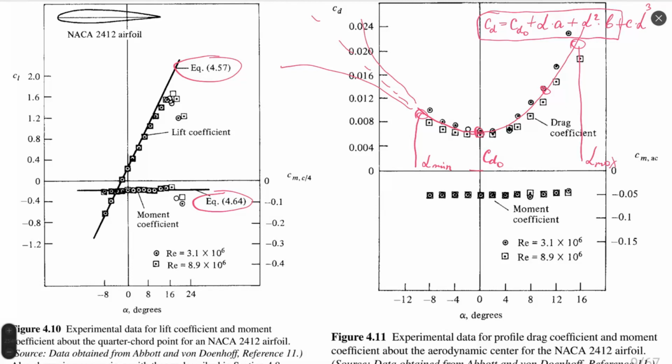It's a combination of influence of lift and drag. When you have inclined airfoils, you might find very different behavior with respect to different Reynolds numbers. So for momentum coefficient, if you can analyze as many points as possible for experimental data and work in between points, a linear approximation would be the best, probably.